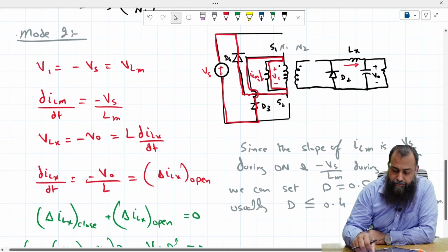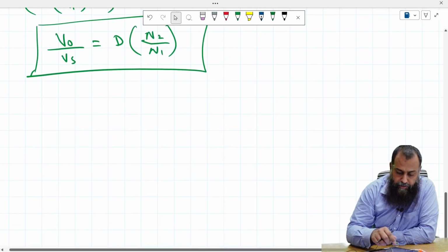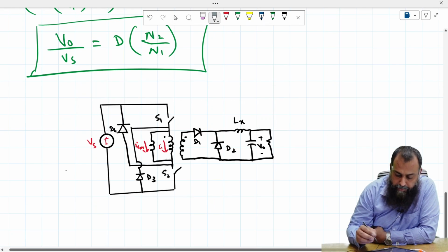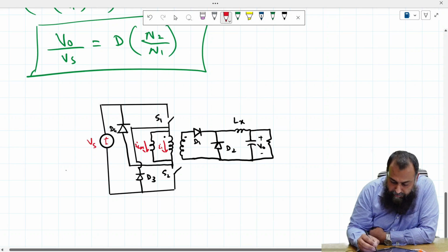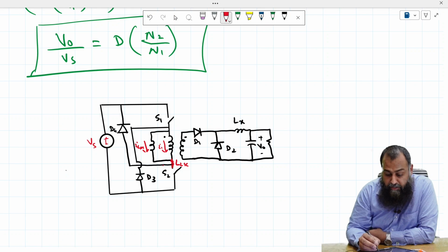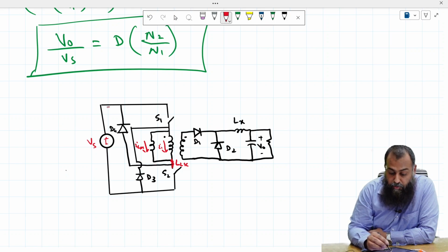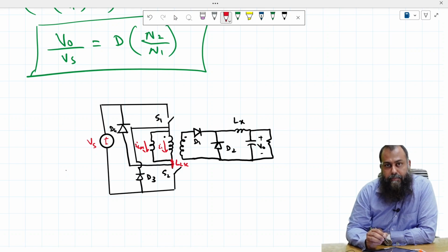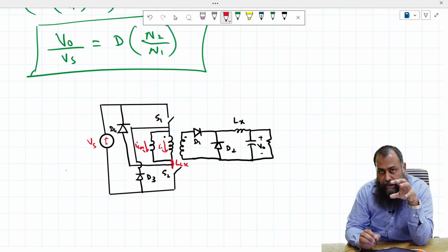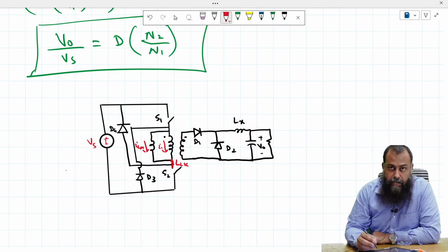So here what we have seen is that using this given topology, now let us have another look at the circuit here. If you assume that we have some leakage inductance LLK here, this magnetizing inductance now has a path to drain its current down to 0 through the diodes D4 and D3, and therefore there is no extra voltage stress applied onto the switches S1 and S2 because of the leakage inductance of any given transformer, and therefore this problem is solved.